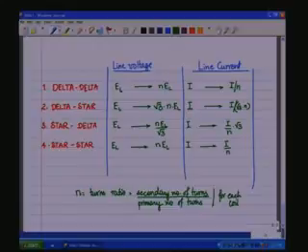In the case of a step up transformer, you see that in the case of delta star connection, the line voltage is higher than the phase voltage by a factor root 3. The line voltage is actually root 3 times the phase voltage, and therefore the coil voltages are going to be lower by a factor root 3, because the line voltage on the secondary star connected is going to be root 3 higher.